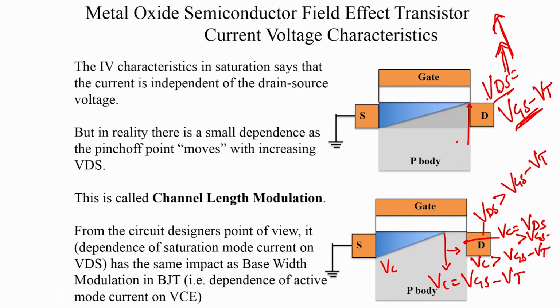So, the pinch off point now relocates to a different region, and as I keep increasing VDS, the pinch off point will start drifting towards the source side.